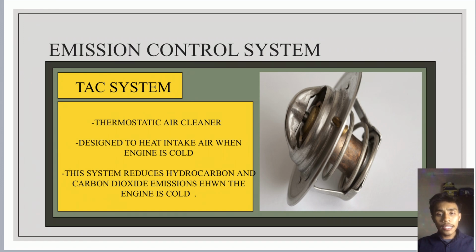Thirdly is the TAC system. TAC system is a thermostatic air cleaner. The TAC is used to provide warm air to the air cleaner during cool startup. This helps to improve cool engine performance and reduce automotive emission by providing better fuel vaporization. The TAC system is primarily used on carburetor or throttle body injected engines.